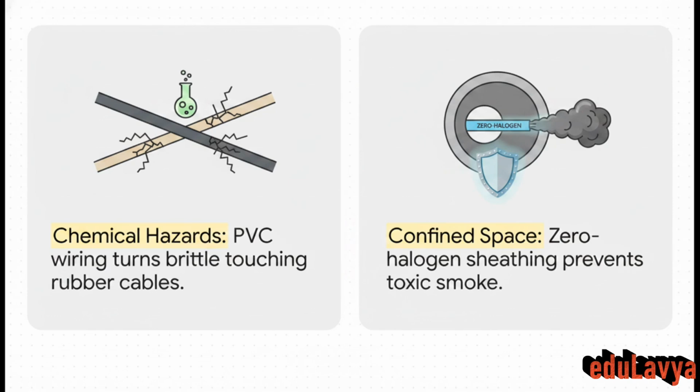For example, if standard PVC wiring is just allowed to rest against rubber-insulated cables, like PCP, the chemical interaction actually causes that PVC to become super hard and brittle over time, totally destroying the insulation. Designers have to literally plan the physical routing to keep them separated.